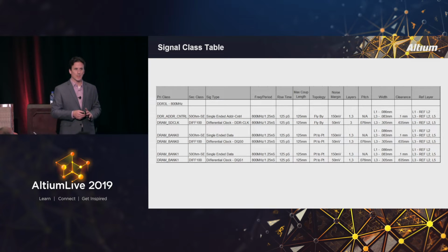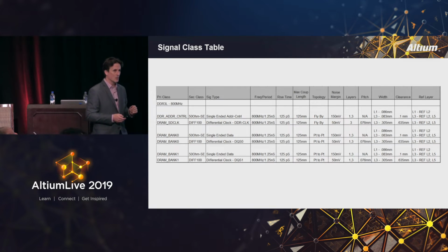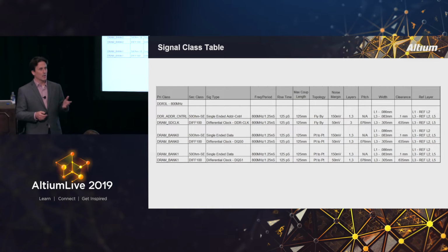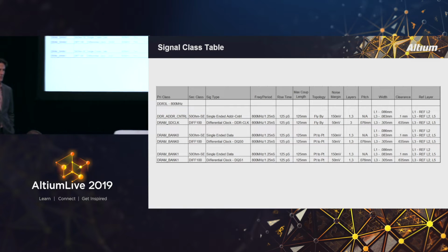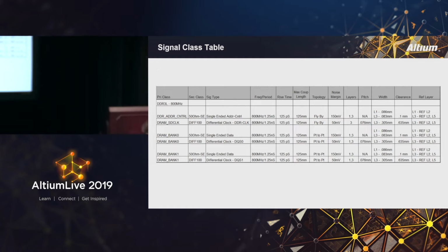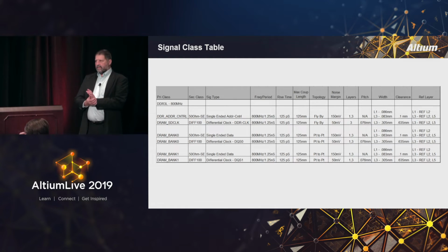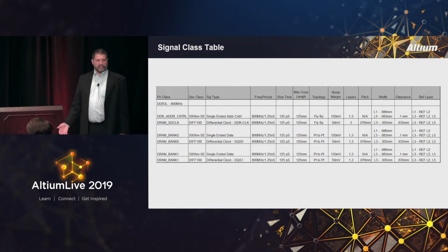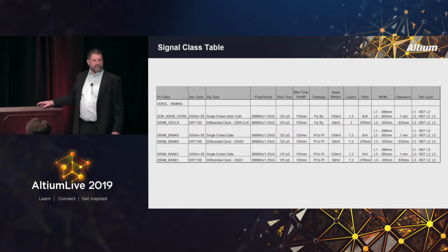So are you estimating how long the signals are? You have no layout yet. I have not done layout. Yeah, he mentioned he was guessing. So he's going to place the memory close to the processor, and we know that it has to take a C-shaped route to get there. We know that there's going to be a data and address bus, and one of them has to wrap around and one of them is going to be more direct. So he's guessing, somewhat conservatively, at 5 inches.